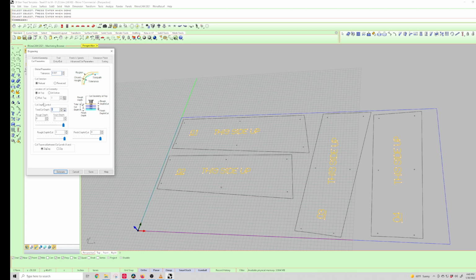So total depth of cut, 0.02, and if you just click on the rough cut, it's going to take that value and just place it there. You could do a 0.02, and then down here do 0.01, and then it's going to do these letters twice to get to that value. There's no reason to do that, so I'm just going to go back to 0.02.